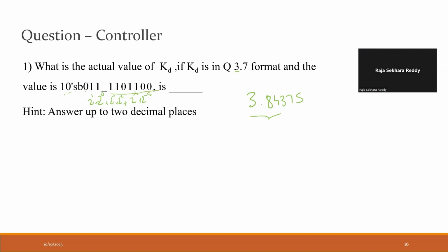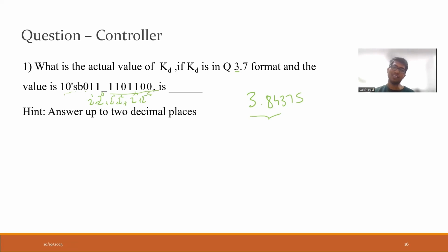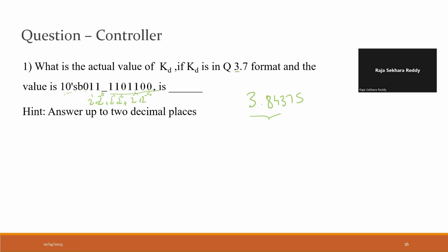Sir, in the last case, regarding the gain bandwidth, as you said, if we manage to keep the gain of the amp less than 1, then we can get the sensed inductor current approximately equal to the actual current, right? I don't know if the bandwidth can be greater than that unity gain bandwidth. That you'll have to check, whether it's possible.